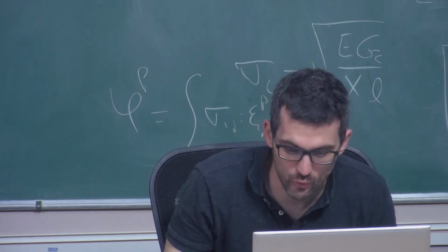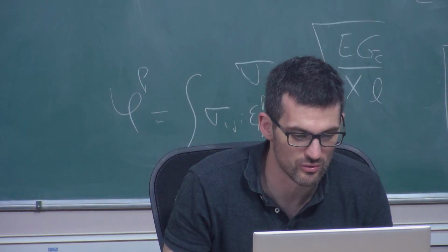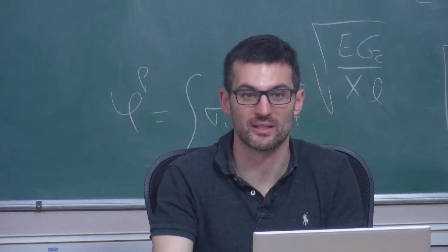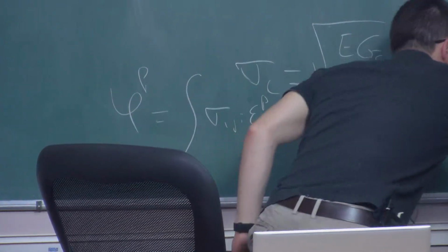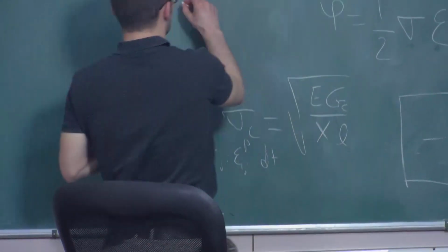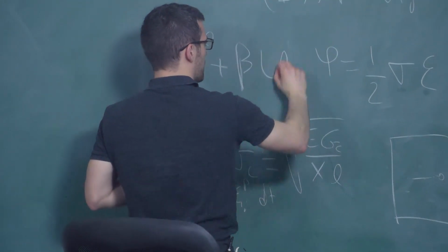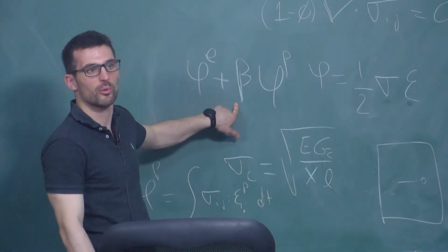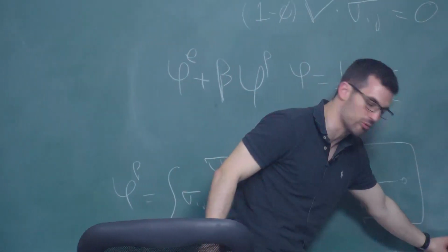As usual, I got good questions during the break. So one that I want to bring your attention to in particular. When we talk about phase field and elastoplastic fracture, we discussed that the driving force could be the elastic one plus some fraction of the plastic one. Based on those Taylor and Quinney experiments, this should be 0.1, so 10% of the plastic work. Again, up for debate, but I think this is the most consistent one.